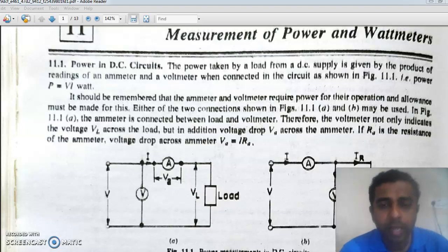So welcome back. In the last few lectures, we have learned about PMMC type of instruments and MI type of instruments. In PMMC instruments, as the torque was unidirectional, you can only measure unidirectional flow of current, so they were mainly used for measurement of DC voltages and currents.